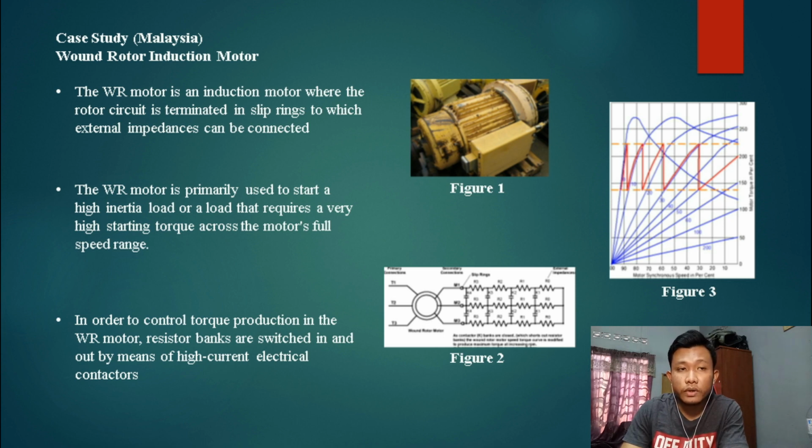If the motor is operated at reduced speeds for most of its duty cycle, relatively more energy is being absorbed in the resistor banks for torque production. Depending on the application horsepower and duty cycle, the energy saving can be in the hundreds of kilowatt hours.